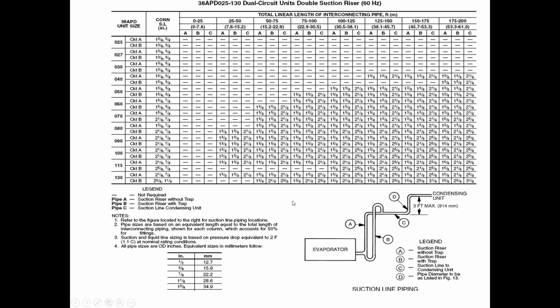Okay. Think about cost. When you're adding elbows, think about resistance to flow. If we did that 4 different times, obviously we're hitting 3 different verticals, right? So we're throwing more elbows at it. And if we're putting a ton of elbows in because of whatever obstacles, you name it, then you really need to sit down and look at how many fittings you have and then add those up.